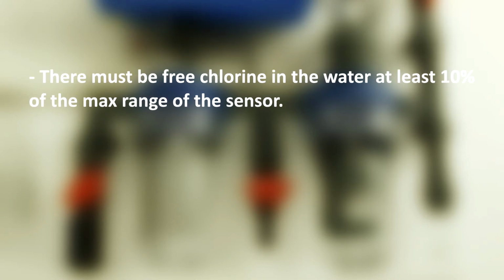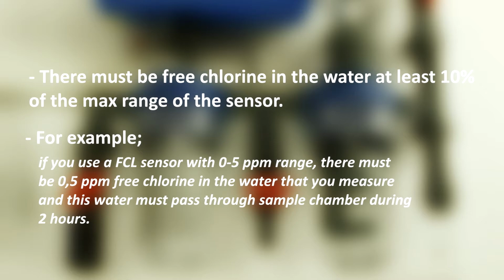Meanwhile, there must be free chlorine in the water at least 10% of the maximum range of the sensor. For example, if you use a free chlorine sensor with 0 to 5 ppm range, there must be 0.5 ppm free chlorine in the water that you measure. And this water must pass through the sample chamber during 2 hours.